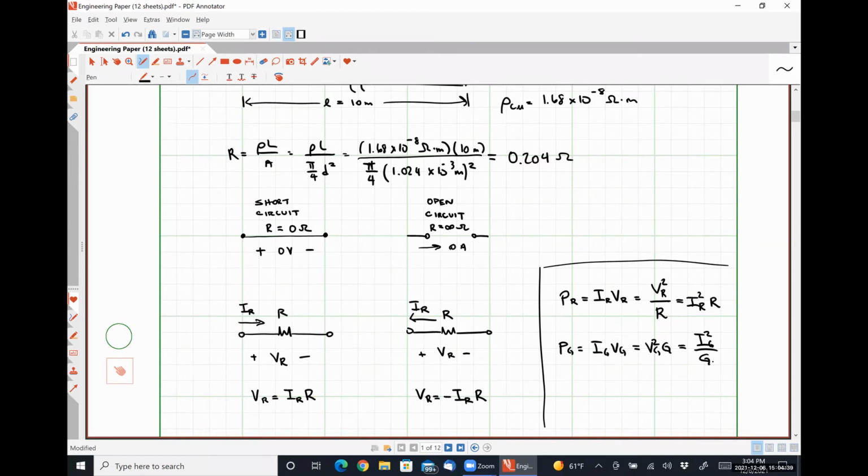You're not going to see it very often. It is just here to annoy you in Circuits 1 for the most part, until three years down the road for you EE students who might happen to take classes that talk about it, okay? So in this class, anytime you have a conductance, convert it into a resistance, and then go about your day. Make your life much, much easier. So simply take the reciprocal of it to give yourself the resistance value, and then just move forward as if it were a resistor, and your life will be so much easier.